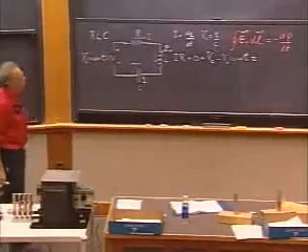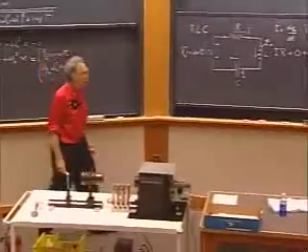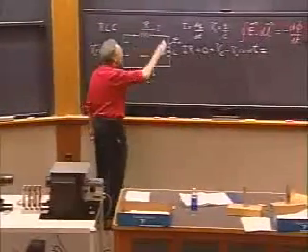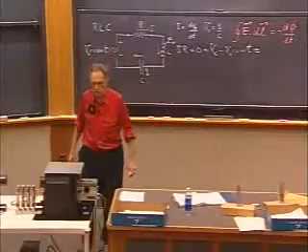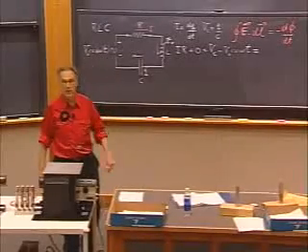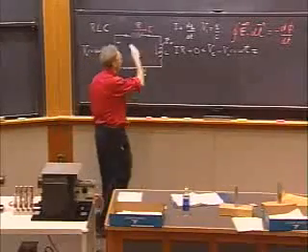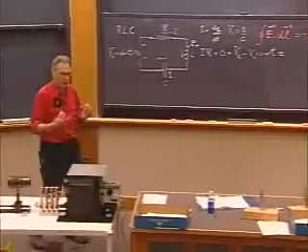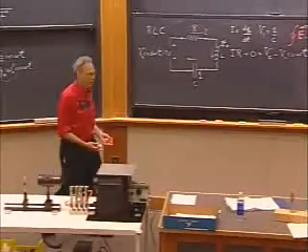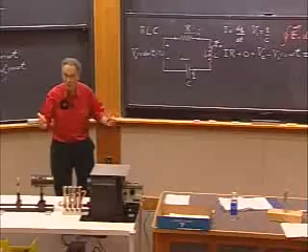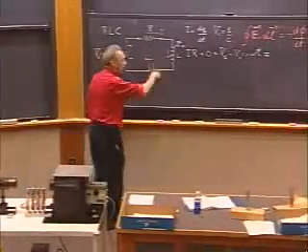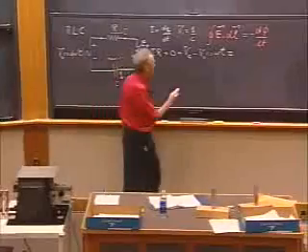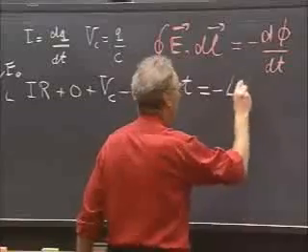The only thing when you apply Faraday's law is you should always integrate in the direction that you have your current assumed. Then it is minus L di/dt. If you do it in the opposite direction, then it is plus L di/dt. I have learned a certain discipline in my life. It took me many years, so you have a long way to go. And I always go in the direction of I, so I never have to think. So this is minus L di/dt.